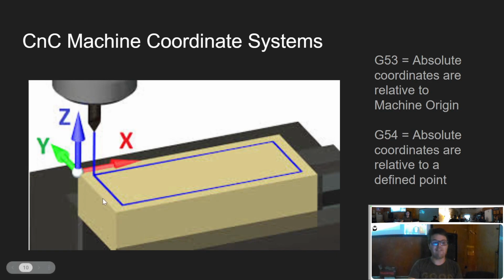What that means is every single program will have G54 at a different place on the workpiece that you're going to do. And you, as a machinist, have to load the block into the machine in the correct place, find where that G54 point is, and tell the machine that's where 0 is, and then it's going to do all of its cuts relative to that point. And if you screw that up, everything goes horribly wrong. So I beat the dead horse now, but that is how everything is done, and you have to remember that, and you have to get it right.